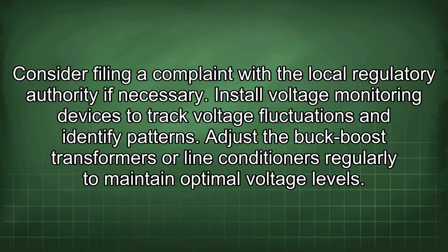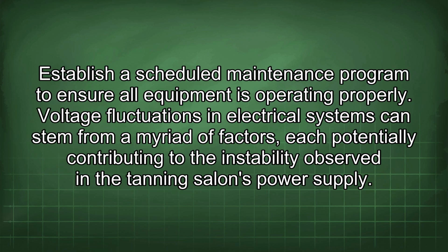Install voltage monitoring devices to track voltage fluctuations and identify patterns. Adjust the buck boost transformers or line conditioners regularly to maintain optimal voltage levels. Establish a scheduled maintenance program to ensure all equipment is operating properly.